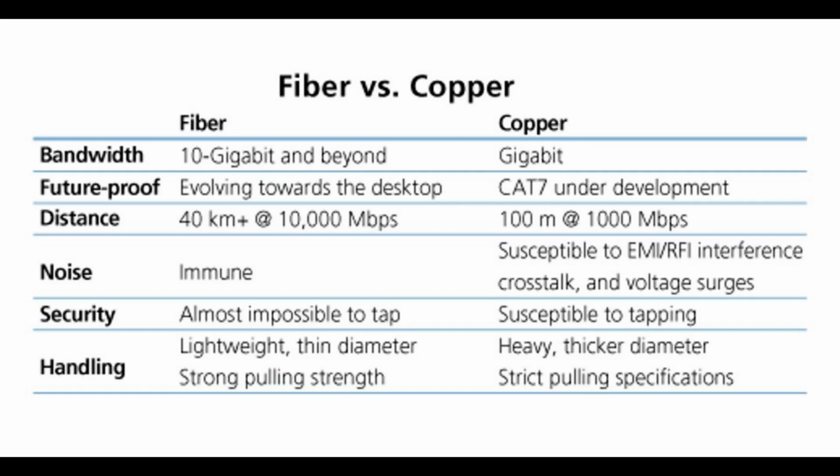5. Types of fiber optic cables. Single-mode fiber, SMF, designed for long-distance transmissions. Single-mode fibers allow only one mode, path, of light to propagate through the core. These are common in telecommunication networks. Multi-mode fiber, MMF, suited for shorter distance transmissions. Multi-mode fibers allow multiple modes of light to propagate through the core simultaneously. They are often used in LANs and data centers.